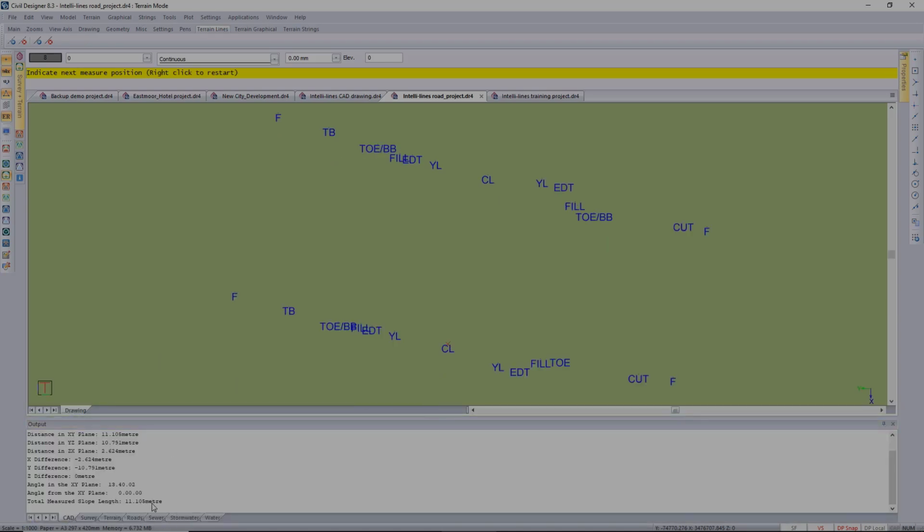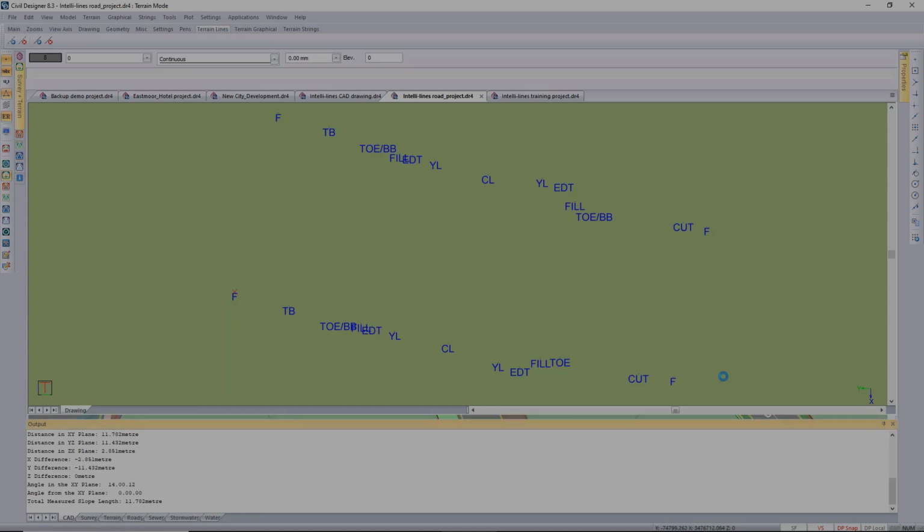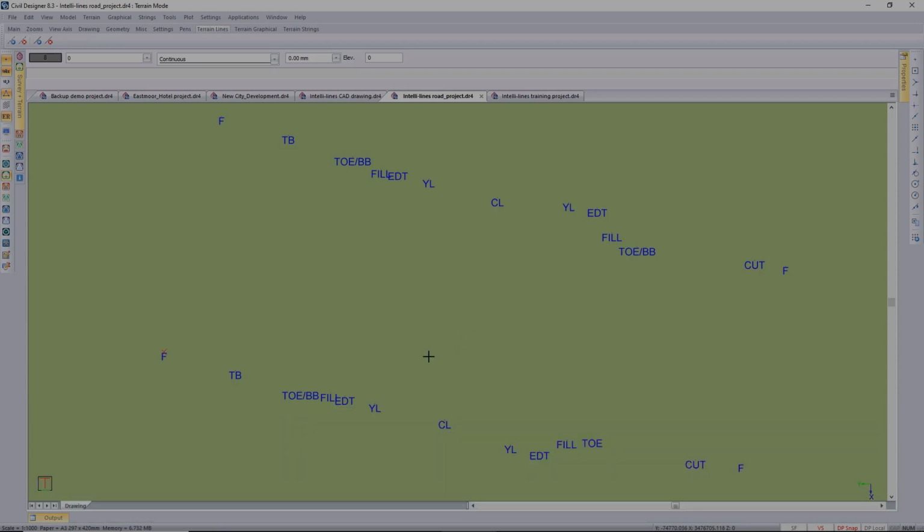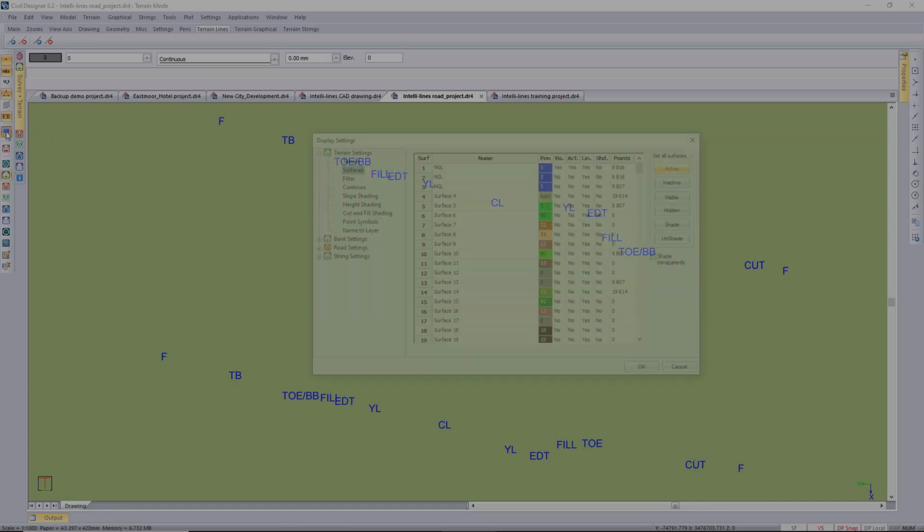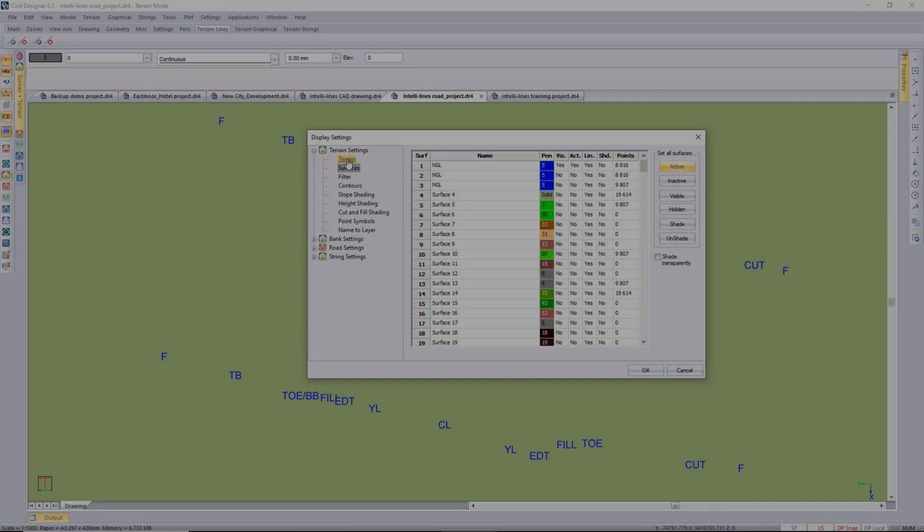So generally the rule is to use about 1.5 times the length between your points. I can maybe do from fence point to fence point. So also under 12 meters. So I'm going to use a maximum line length or search distance of about 15 meters when it needs to join from one point to the next closest specifically named point. Okay, so I'm just going to display settings and I'm just changing my text size.